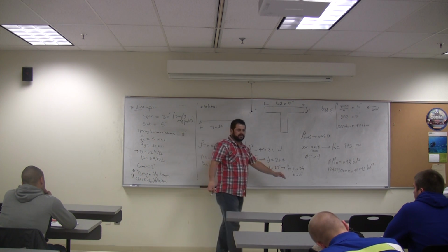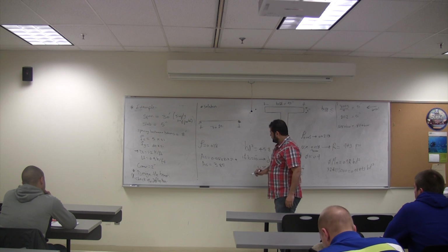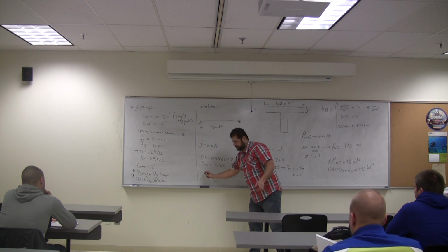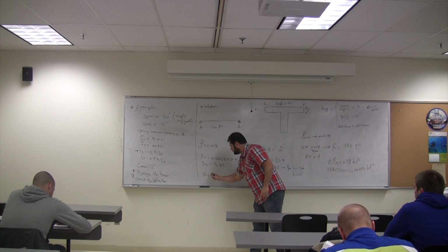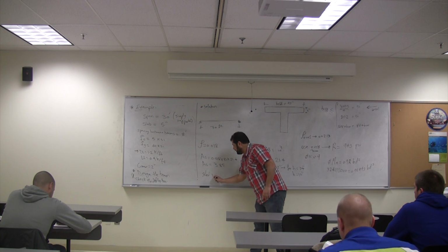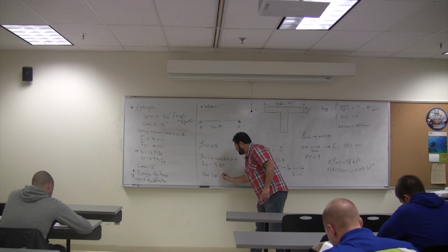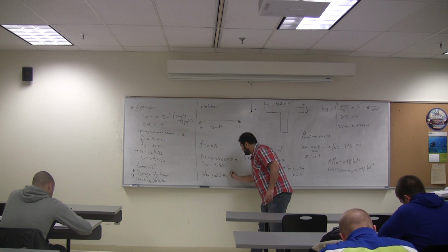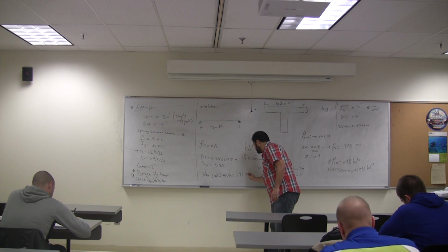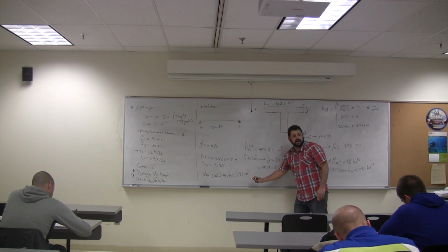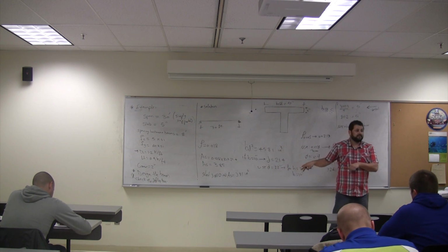I'm going to show you in a minute why, because we're taking 24 instead of 21. So select 3 number 10. As equals 3.81 inch squared. This is compensated by the d we have.